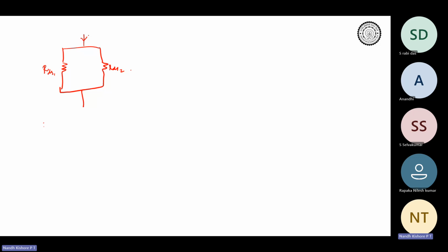Okay. And total current is 60 amperes, let's say. And due to some mismatch in RDS, it may not be exactly the same. The RDS may be here and there a few milliohms mismatch. Let's say RDS1 is less than RDS2. So obviously your I1 is going to be greater than I2, correct?